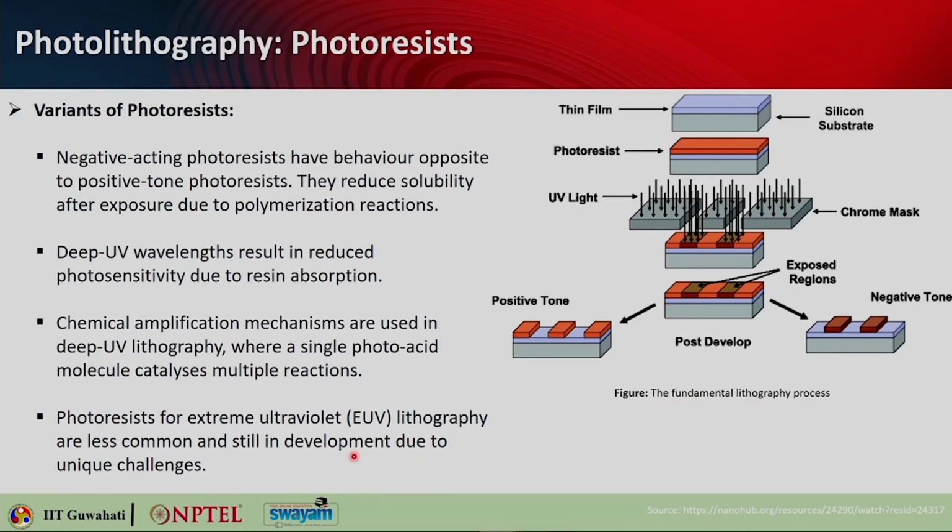Photoresists for extreme ultraviolet lithography are less common, but they are still in development due to the unique challenges. So, you can understand that extreme UV lithography is still not very popular because the material that can help this technique is still under development, whereas the UV lithography ones are well developed. Even the deep UV lithography ones are also available.